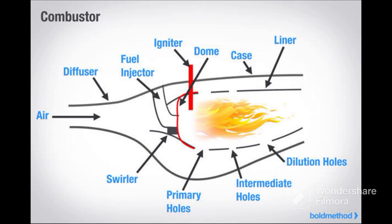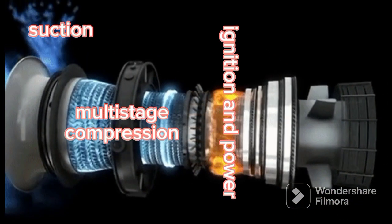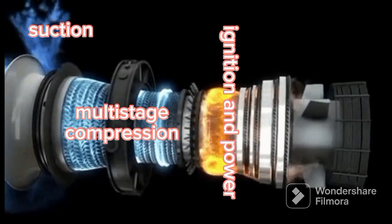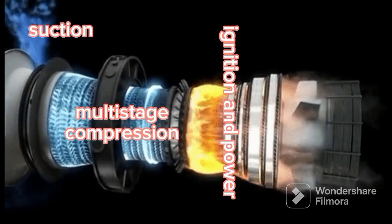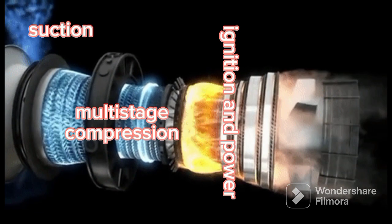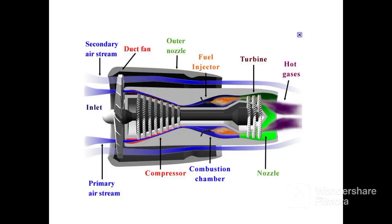Number 6. Turbine. The turbine in a jet engine is a critical component that is responsible for extracting energy from the hot gases produced by the combustion process in the engine's combustion chamber. The turbine is typically located between the combustion chamber and the exhaust nozzle and is driven by the hot gases as they expand and flow through the turbine blades.